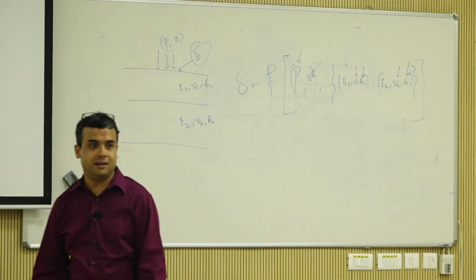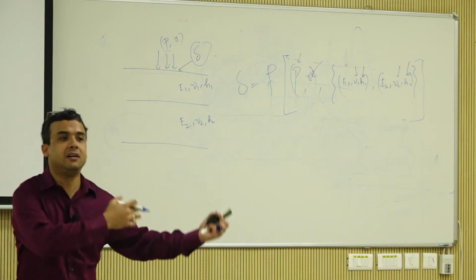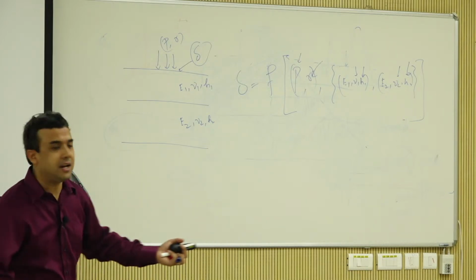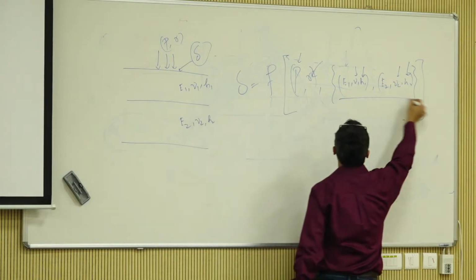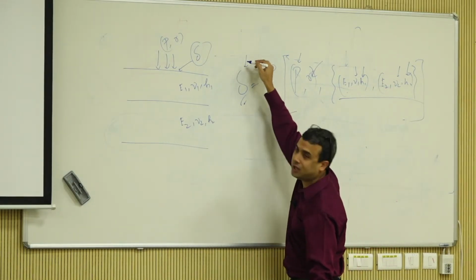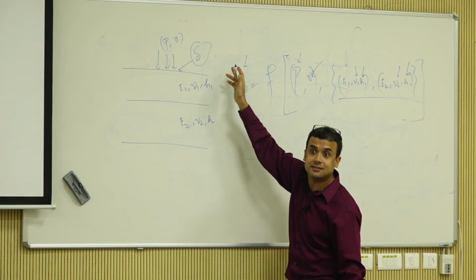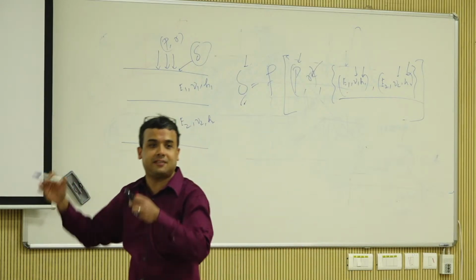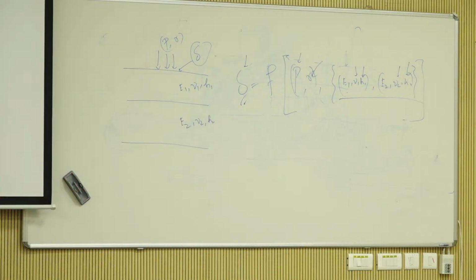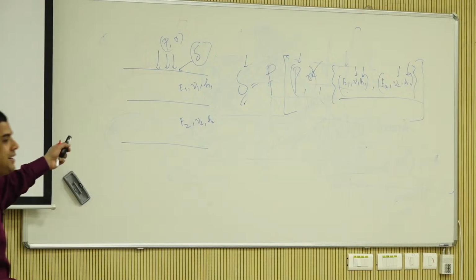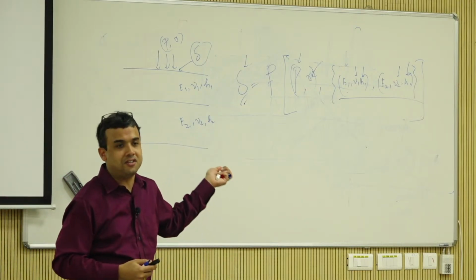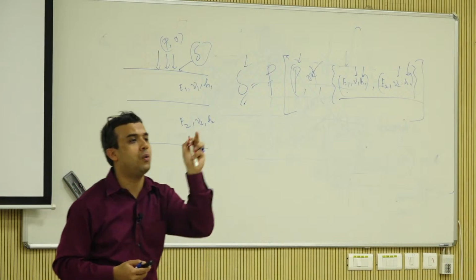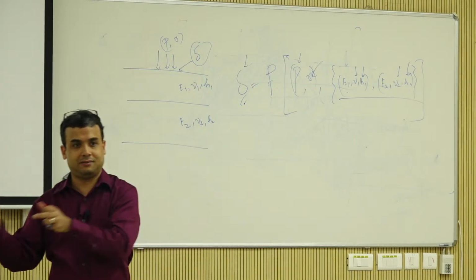E, right? So what you're going to do is back calculate the E. The forward calculation is when you have all the properties and you are trying to find deflection. Oh, by the way, in the field, do you know delta? Yes, because you're running an FWD test. You know the delta. So now you have delta and all the others, and you're going to back calculate the E. That's called falling weight deflectometer layer modulus back calculation. It's no rocket science. The mathematics is probably a little complicated, but the concept is very simple. You don't have all the forward calculation properties, so you are just back calculating.